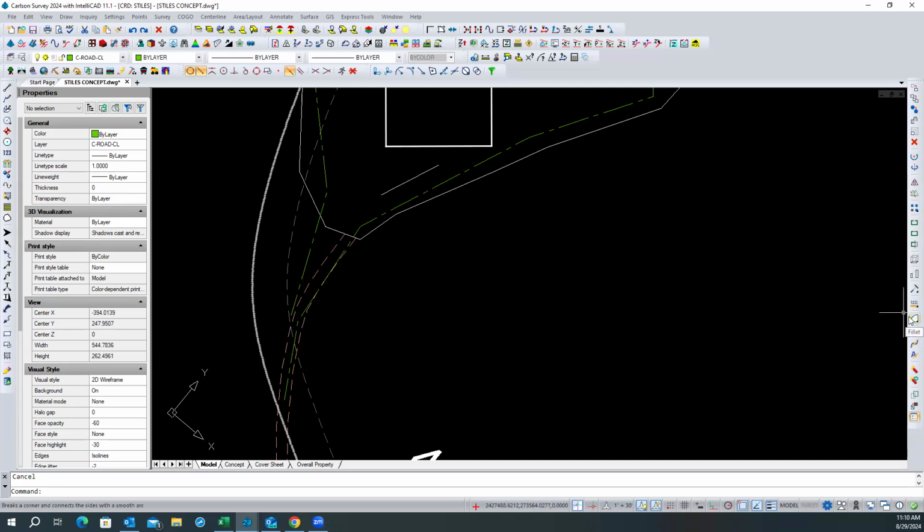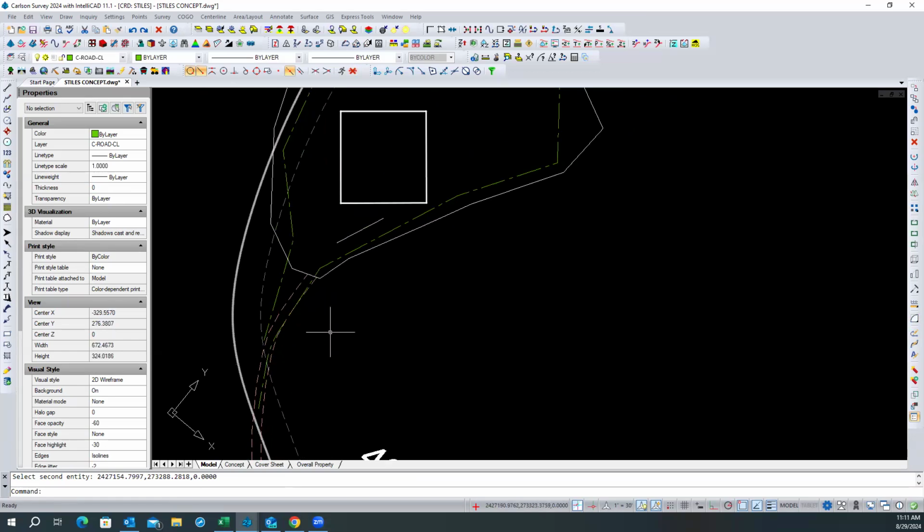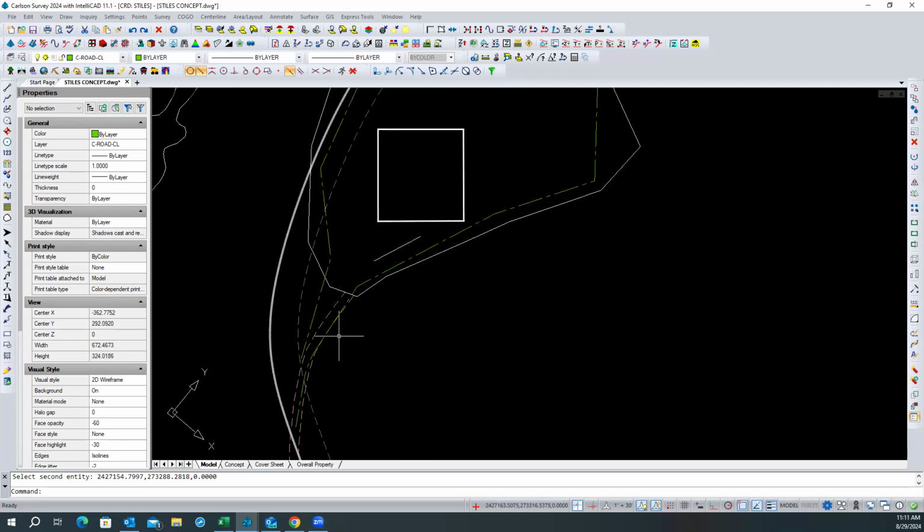And I'm just going to do these with CAD tools. I'm going to use this fillet tool. Okay, so I choose that, I type R for my radius of 75 feet, and I select this and that. All right, so now you see I've got a nice arc. We're going to put in some others, but I just wanted to see, that's a way to sort of get a gauge on the size of these features. But sure, we can do this pretty nicely as well, maintaining with the centerline editor.